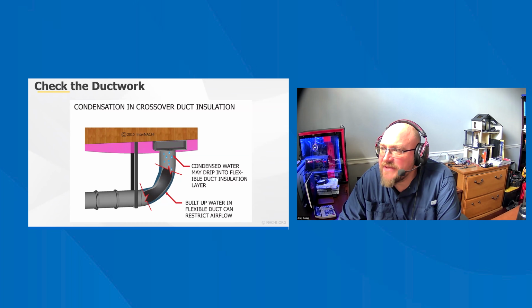The ductwork of the HVAC system in a house may be checked by the inspector. If the ducts run through unconditioned spaces in the house, such as crawl space or an attic, then the ductwork should be insulated. The ductwork should not leak air. Leaking joints should be repaired with mechanical fasteners and then sealed with water-soluble mastic and embedded fiber mesh. Gray cloth duct tape should never be used for this purpose. It degrades, cracks, and loses its integrity and bond with age.